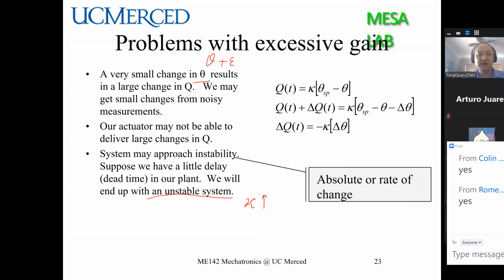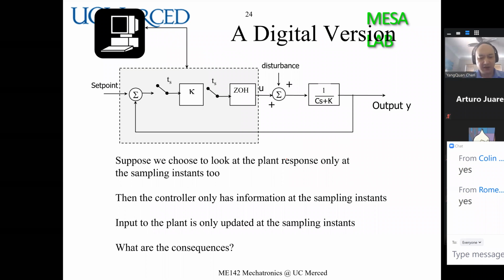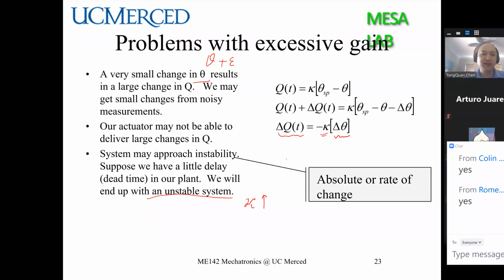Okay. All right. So here is the same. If you have some changes in here, noise, then your control signal will also change very big. Then that will make your actuator act so often that soon it will get worn out or you need to replace it. So that's not desirable. So then, of course, you need to think about using an integration PI controller in this case.